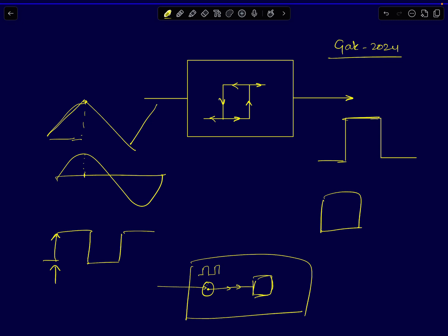Okay, so if you recall in our first discussion, what I've shown here is just a symbolic representation of a Schmitt trigger. This curve here shows the hysteresis. Usually you will be feeding a sinusoidal signal or a ramp signal to a Schmitt trigger, and the output of the Schmitt trigger will be a perfect square wave output. Remember, a square wave output is a signal whose transitions from low to high values will be sudden. It will be instantaneous. It has to be instantaneous.